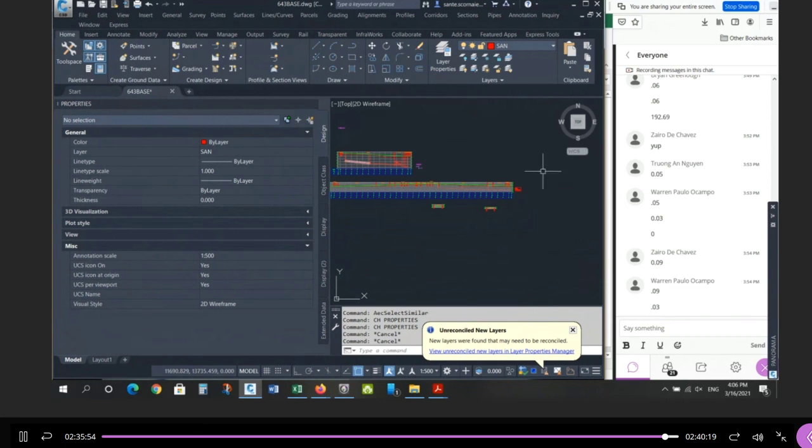Okay, so I'm pretty much done my design, right? Except I don't have all the labels. If you bring in all the labels, don't waste time moving them around until you bring in your storm sewer. And then you can manipulate, make sure that the labels aren't on top of each other. Because you don't want to move these and then overwrite them with the storm and have to move them again. Okay, that's some advice I gave you last semester.